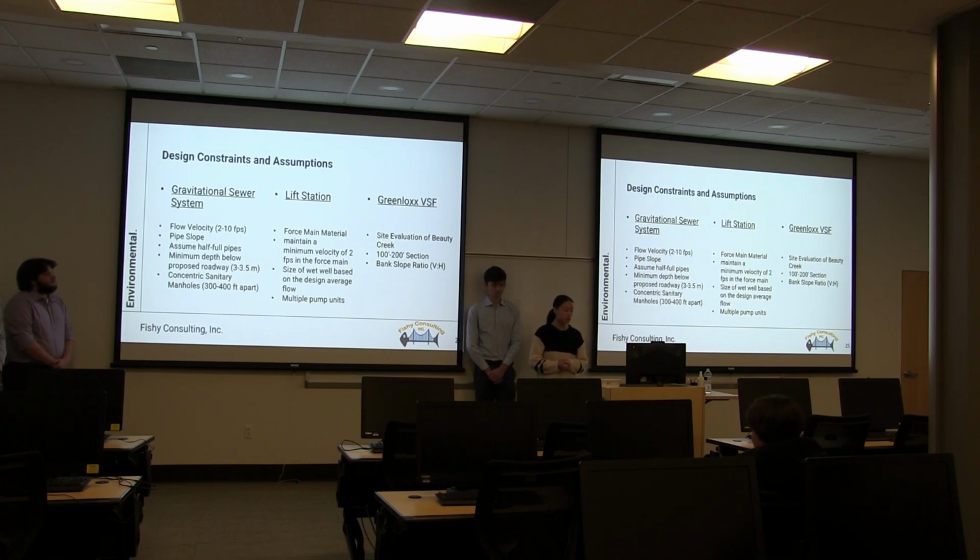Moving on, I'll also need to design a wet well. The size of this wet well will be dependent upon the average design flow of the system, as well as keeping a retention time of a minimum of about 30 minutes, which is a standard recommended by the Ten State Standards as well as the City of Valparaiso. In addition, multiple pump units will be needed in the lift station. Should one be out of service, the remaining units should be able to handle the peak hourly flow.